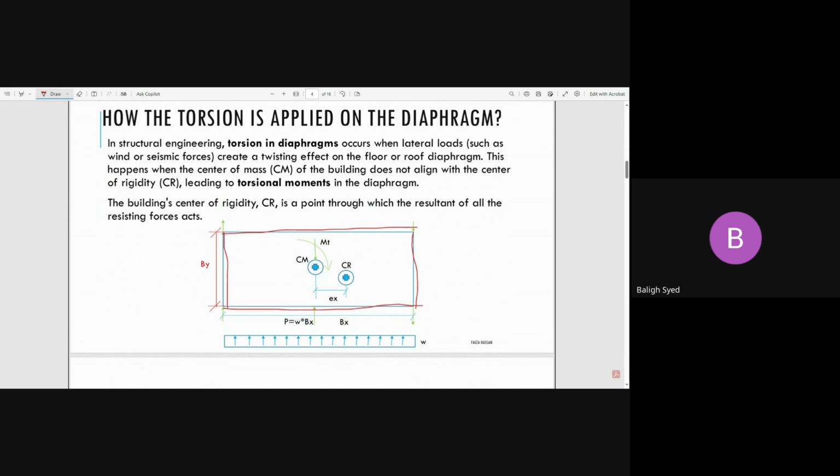Let me give you a simple explanation of why it happens, even in a very ordinary, straightforward, symmetrical structure. Whenever you have a 5-story or 6-story building, you have openings for the stairs, for your elevator shaft, or for some other purposes. We sometimes have big chases, right? All the ducting, cabling, and critical piping go through those openings. So that introduces an unsymmetrical situation in the entire plate.